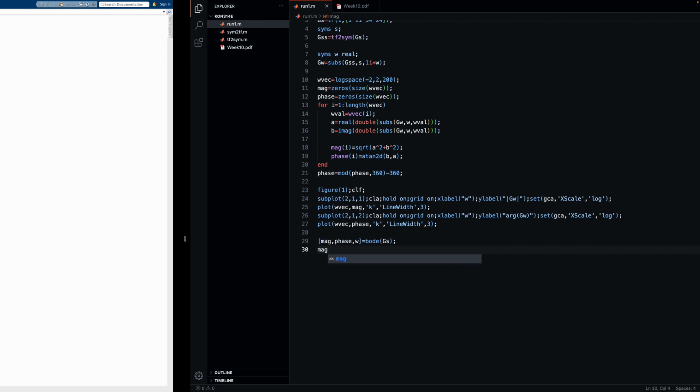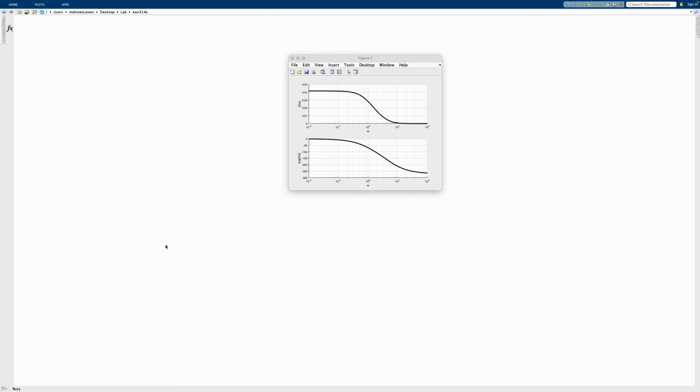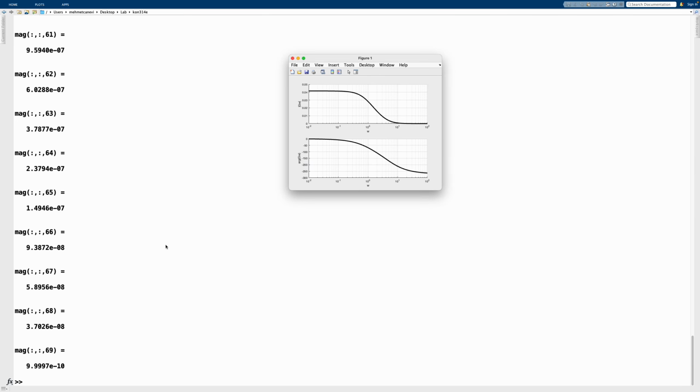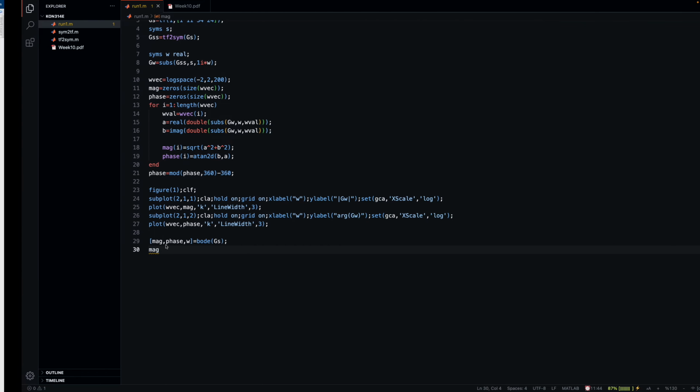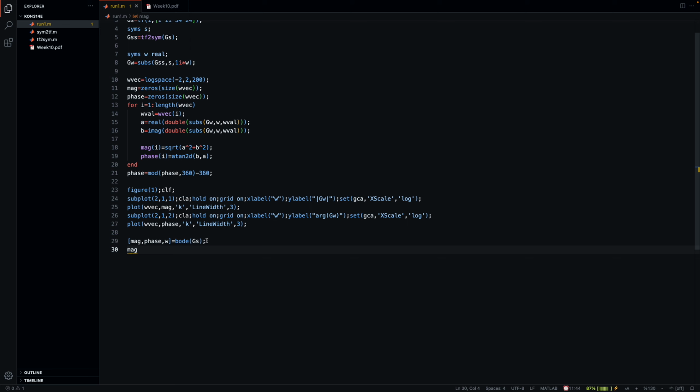But then again, the magnitude here with the bode command is a little bit different than we expect it to be, because it is possible to have multiple input, multiple output systems, MIMO systems, and then there would be some input channels and output channels, and between input and output there will always be a Bode diagram. So the bode command is basically prepared to work with that.